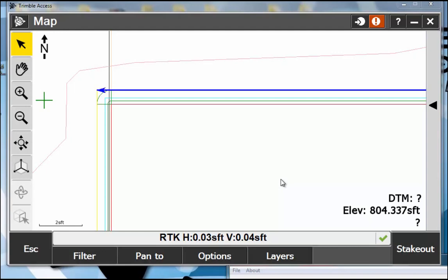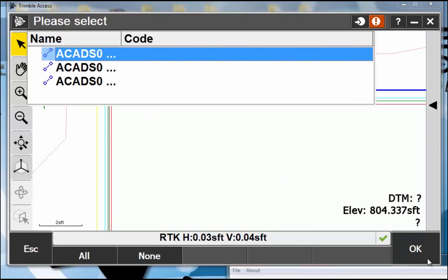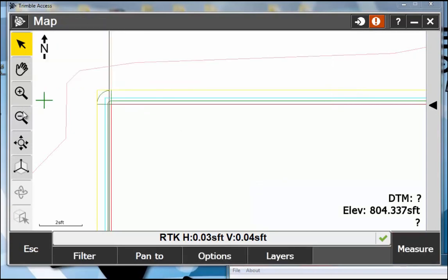But the disadvantage we get with DXF files is that I'm not getting a continuous alignment profile. Right? I'm basically just getting a line segment, a curve segment, a line segment, a curve segment. That may or may not be bad depending on what you're trying to do, but the more I worked with Brian through some of the staking stuff, the more I'm a believer in using the alignment method, where maybe the DXF is just more your reference.